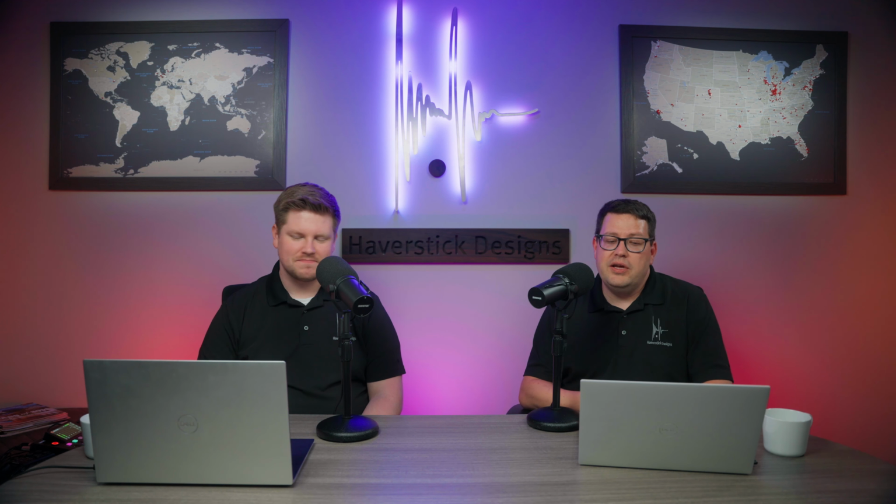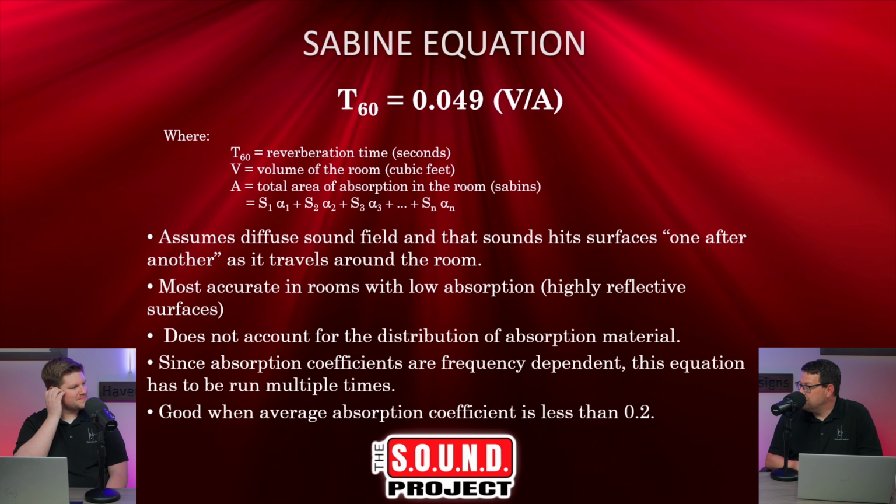But if we look at the equation, and I won't get too far into the weeds with this, but equations are fun. I'm an engineer by degree, and I like digging into these things. So I'll show a few equations here. The Sabin equation is the T60, which would be the reverb time. Sometimes it's written as T60 or RT60. It is equal to 0.049 multiplied by the volume divided by the total area of absorption in the room.